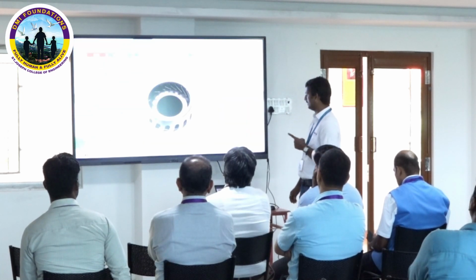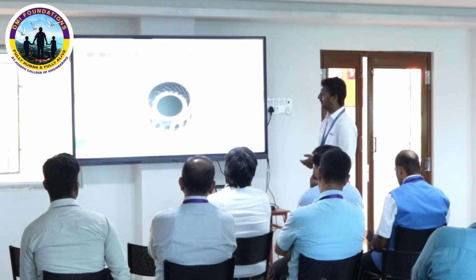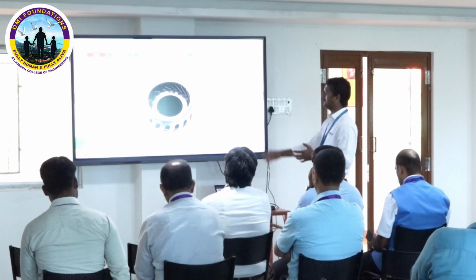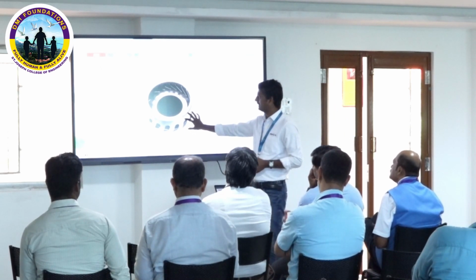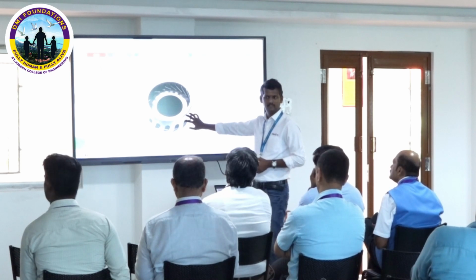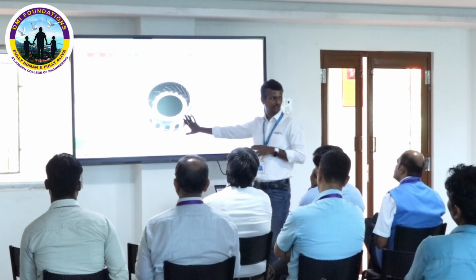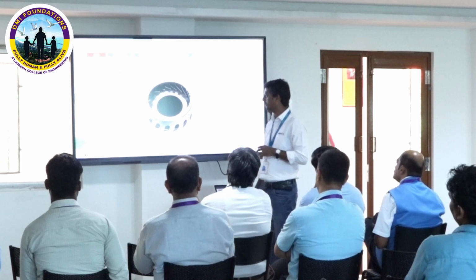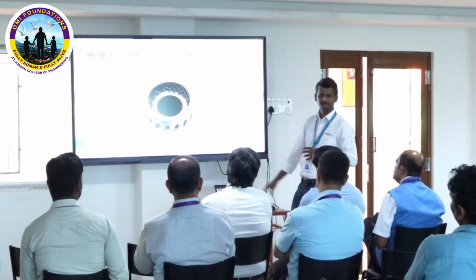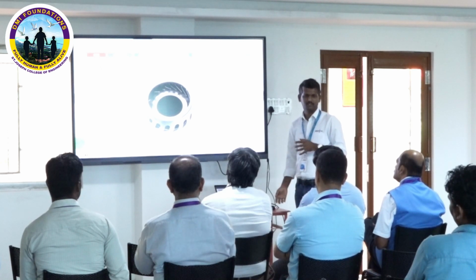In the case of the aviation sector, we have this inner ring component, and we have discussed a lot about it. But actually, what we will do here is this is not printed as it is. This is not the part which is in the as-printed condition. We do machining, we provide some stock material over it, and we remove the material from that. Okay? There is a machined part you can consider. We bring it into a near net shape. After that, we do the machining.